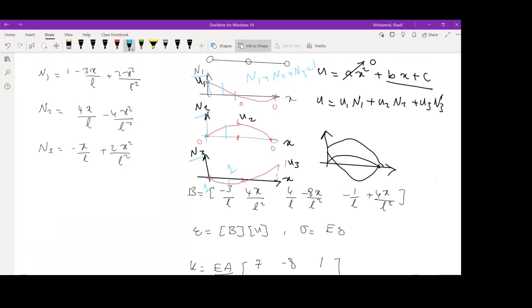I said that this is very useful for quadratic displacement fields, parabolic displacement, or if the displacement field would look like a parabola. And this would be the case if we do a distributed load. A uniformly distributed load would lead into this type of curved displacement field, the second order polynomial displacement field. Now, if it is the case, then when we solve this type of problem, we should be getting the exact displacement field.